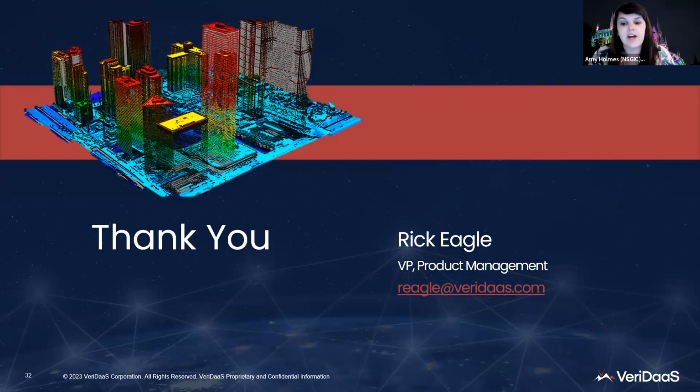Zimmerman asks, is land cover and land use classification still possible in comparison to linear LiDAR plus imagery? Oh, and a second part to that question was, can you capture drainage infrastructure using the oblique capture and overlap? So the answer to the first question is yes, for the land cover. Some of the tools may not be tuned for Geiger mode, but we could look at that, and we could do very similar land cover work that happens with linear.